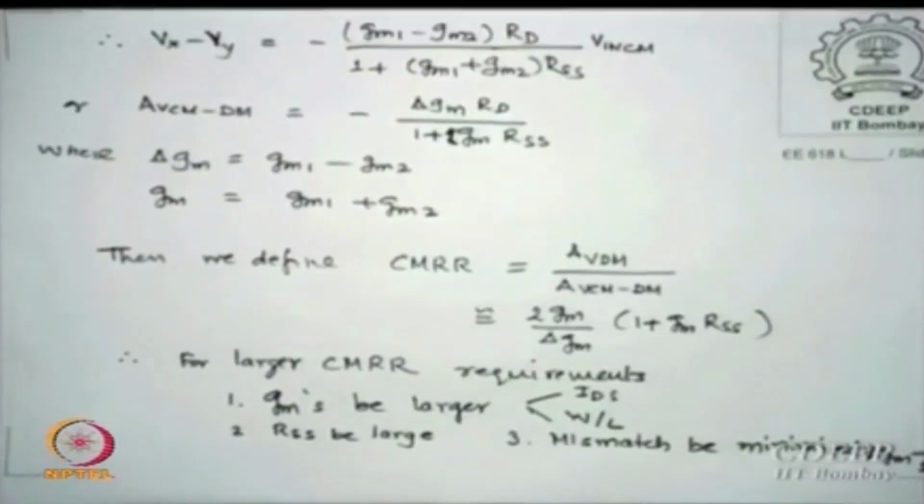So if you change something somewhere to get another spec, this also will get affected, and therefore do not see CMRR as a fixed spec. It is a spec which is to a great extent variable, greater than, oh I can't tolerate less than 80 dB, fair enough, okay, but do not say it has to be 80, it can be 85, 90 or whatever it is, okay.